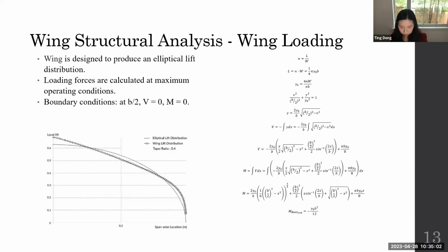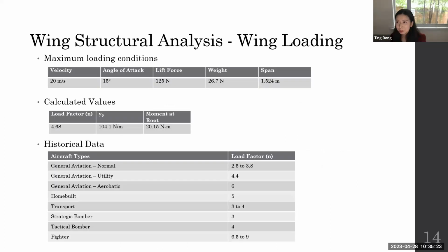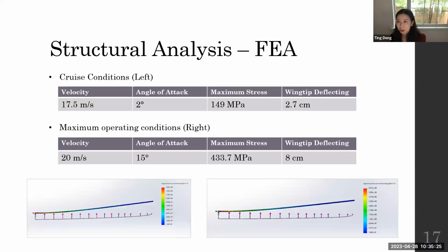So I would say that is a more standard way to do structural analysis. Just want to make the logic very clear here. And also, I definitely agree with Jacob on the FE analysis on page 17. We normally do not prefer to use SolidWorks for FE analysis. So you can use ANSYS, you can use Abaqus, you can use Nastran. Use some professional FEA software, because SolidWorks is really not for FEA analysis.